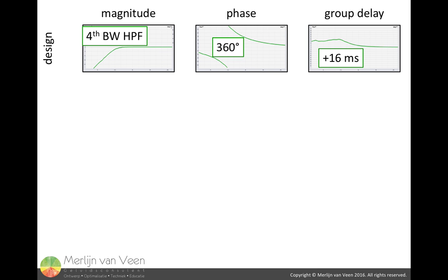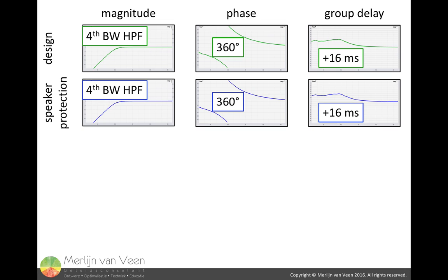Typically, the speaker is protected from damage by an electrical high-pass filter, again near the tuning frequency. The topology is often Butterworth, because of its low frequency extending capabilities. The Butterworth topology exhibits only 3 decibels of attenuation or half power at the corner frequency. Typically, fourth order is used, introducing another 360 degrees of phase shift at the tuning frequency.